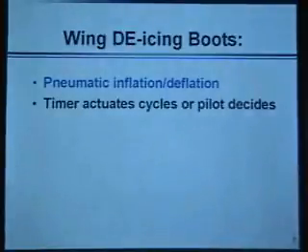If you turn this on too soon, then the ice will end up forming around the maximum inflation area of where these are, and then of course you can think about the lack of laminar flow. It's going to be really turbulent, and you're going to have tons and tons of drag. These boots are typically run along the length of the leading edge of the wing.